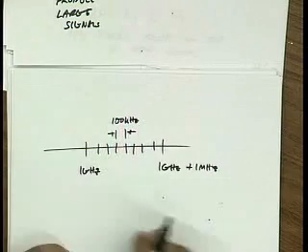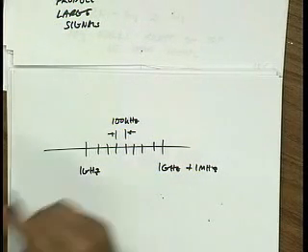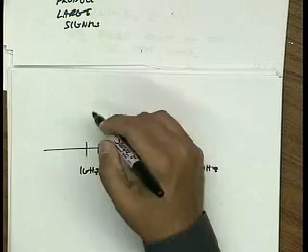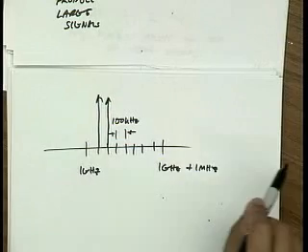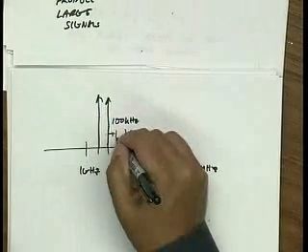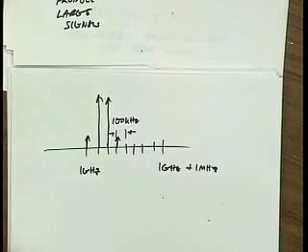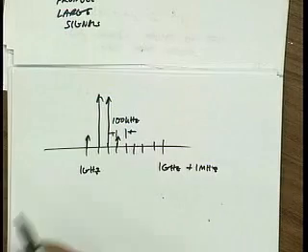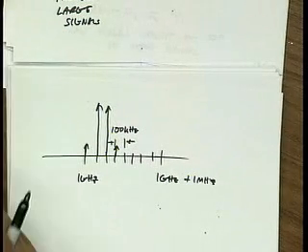Now 100 kilohertz is a good enough bandwidth to carry voice, even FM modulated voice. So that seems very reasonable, except you say this is very narrow band, so if I have 2 channels here, 2 people talking, second order distortion is going to fall way out of band, right? But their IM distortion is going to fall into channel 0 and into channel 3. And if you happen to be on channel 0 or 3, you're going to get hit. Okay? Good question.